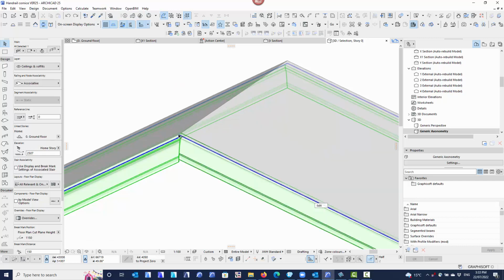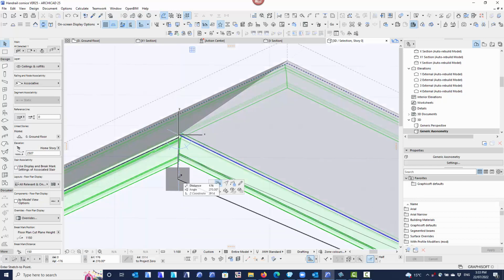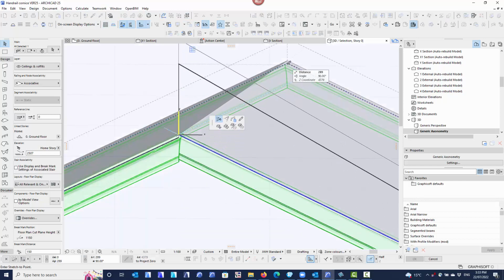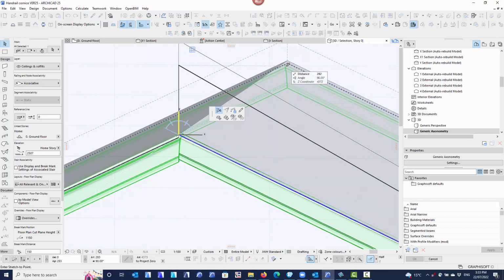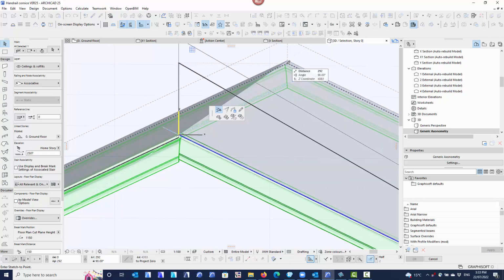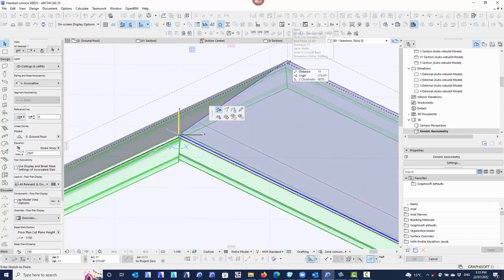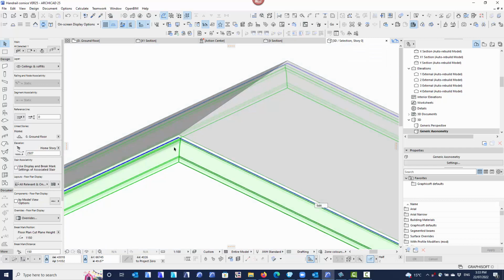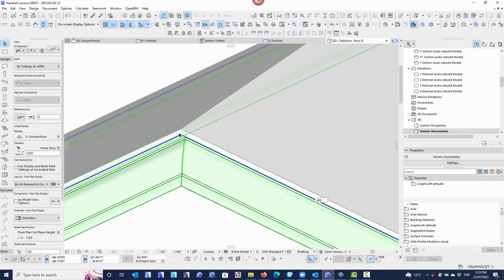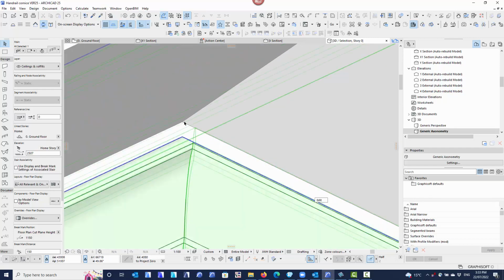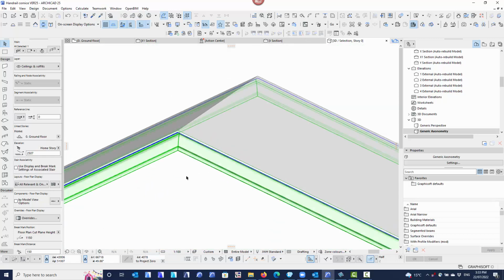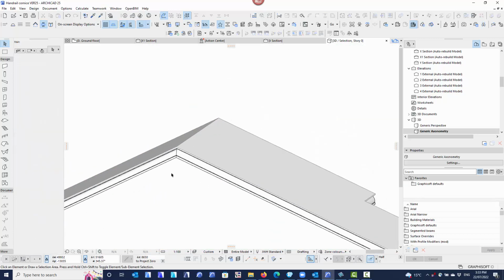So drag that node, lock it vertical, but lock it to that height, and you can see that if I'm careful and not move my mouse, and I lock it to that height, it locks to that height. If you drag it onto it, basically above it in a vertical line, and link it to itself, it won't unassociate, it just reassociates back to that point. So that's something to watch out for.